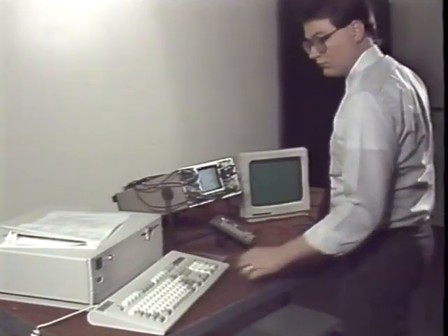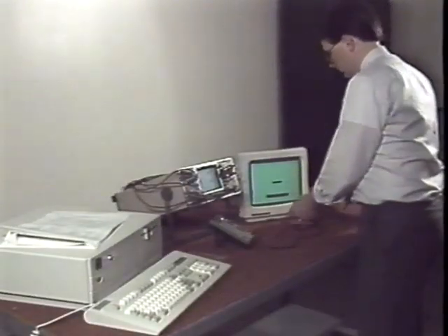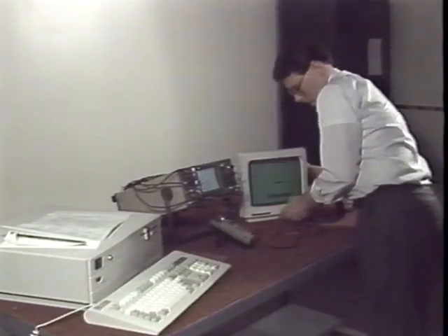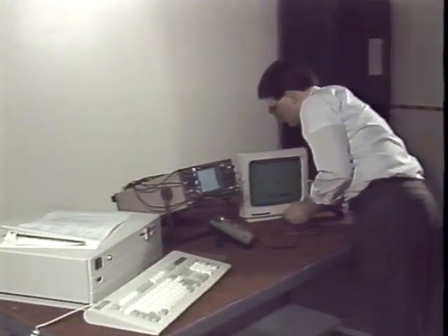Next, reconnect the video, select a full white screen, and set external brightness to minimum. Then we adjust another internal control until video is just barely visible. This is the lowest brightness level the user can obtain. These adjustments allow the user a wide range of brightness levels without wasting any external adjustment range on levels that are always black or that always show a raster.